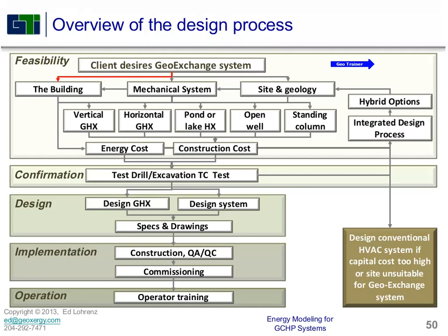for the system they were proposing, and we knew that by putting in more efficient lighting, it could drop that by about 50%, or about 400 kilowatts, or close to 1 million BTUs per hour. That was a big deal. That reduced the size of the ground heat exchanger and the cost of the ground heat exchanger by about $600,000. So in other words, by putting in high efficiency lighting, they would save $100,000 on the cost of the lighting and the ground loop. So that's why I'm saying it's a very important aspect of the whole design process.